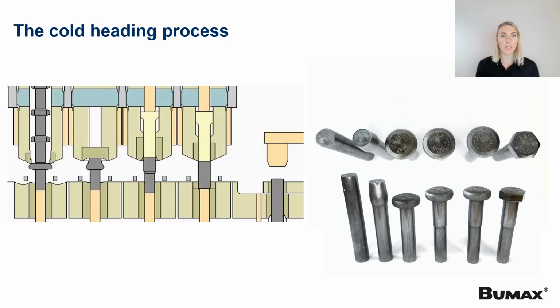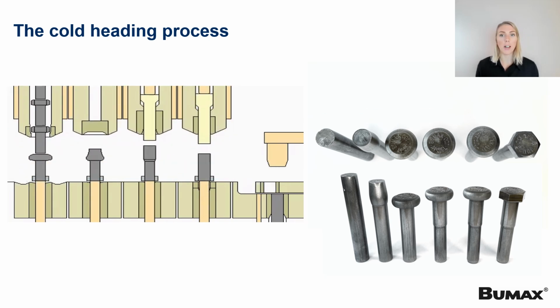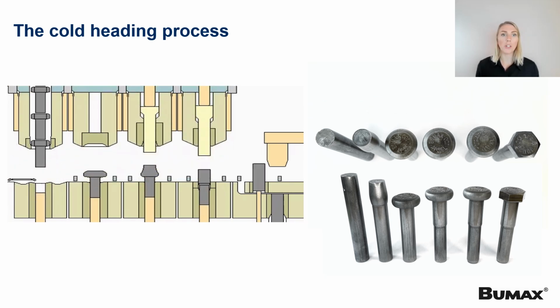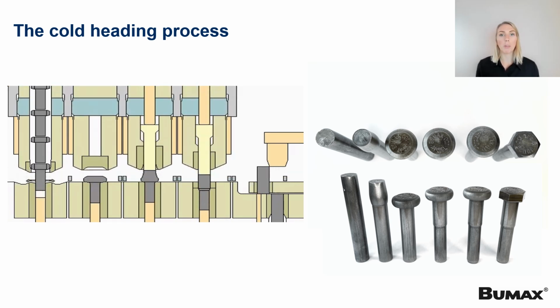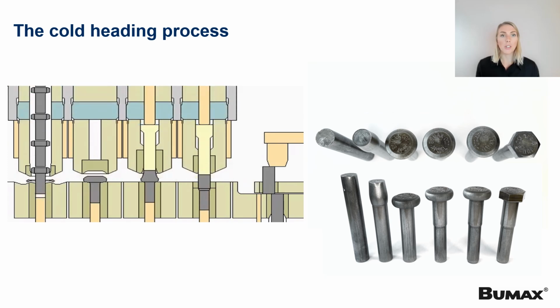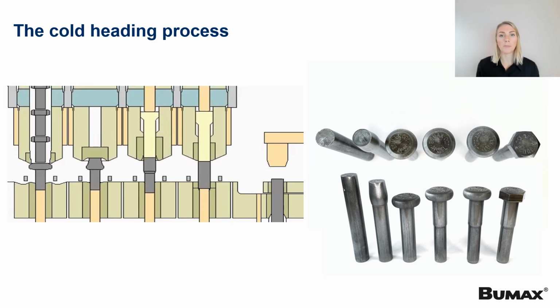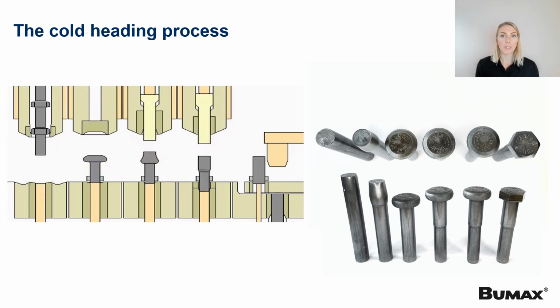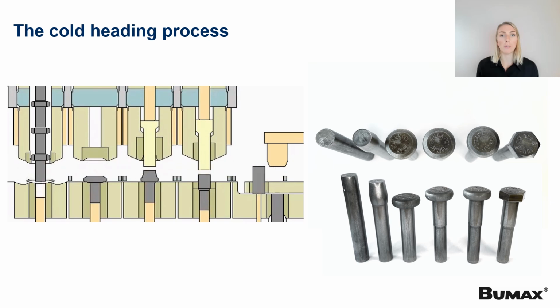The wire is fed into the forging machine, and when the metal is compressed within the die, it is important to introduce just the right amount of material, often within plus or minus 1% or even less. Too little material won't fill the die, making a bad part. Too much material can result in a malformed part or produce flash that needs to be removed.